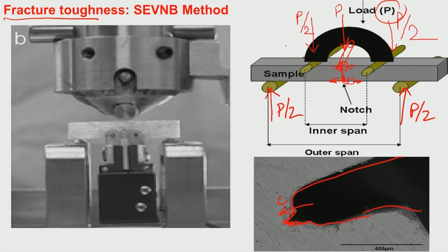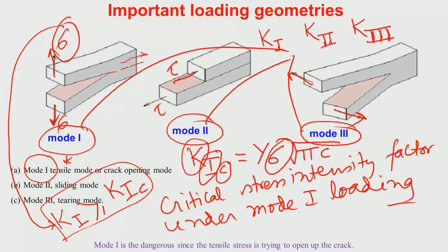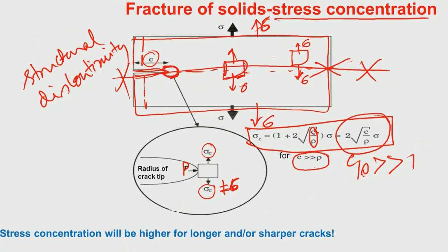You can use either 3-point loading or 4-point loading, but 4-point loading is by far more preferred because here this much region would be under uniform tensile stress. In case of 3-point loading, only a limited region will be under uniform tension. Therefore, any crack present in this uniform stress region can simply propagate, leading to failure of the entire sample. This is how fracture takes place in brittle materials, and that is how experimentally one can measure the fracture toughness of a brittle material like ceramics.